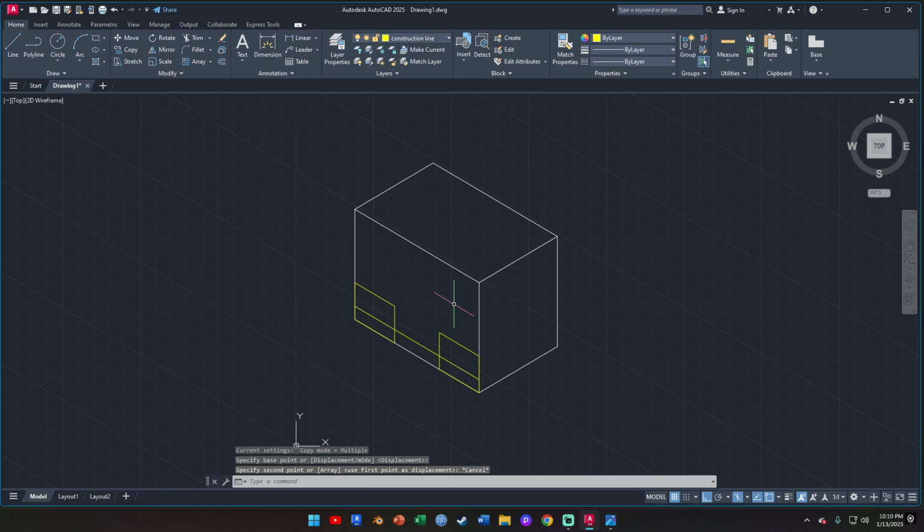Remember, we're on isoplane left, meaning that it's only going to be drawing whatever is on this face here, the left receding axis. So in order to move this line to where we want it, we have to use the top isoplane since we're drawing on this plane now. So you click on the arrow here and you switch to isoplane top.